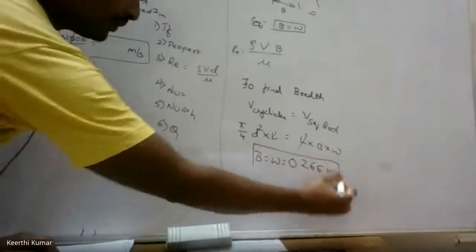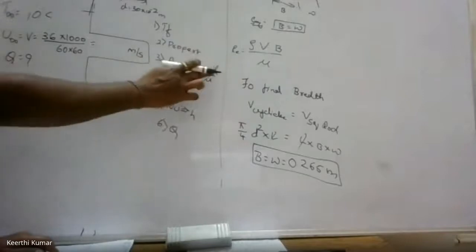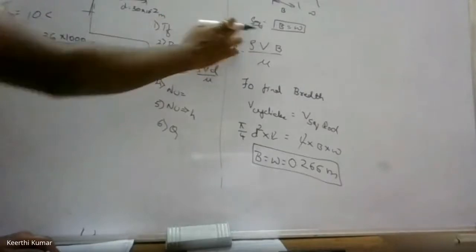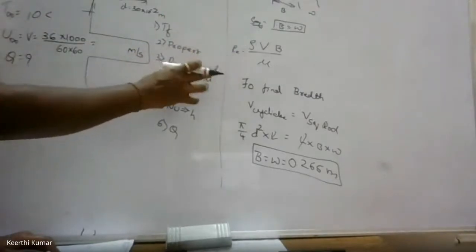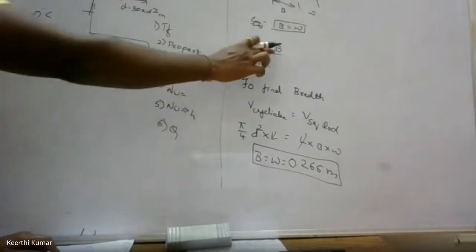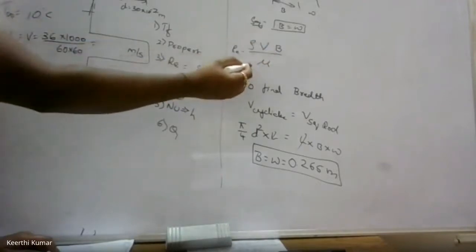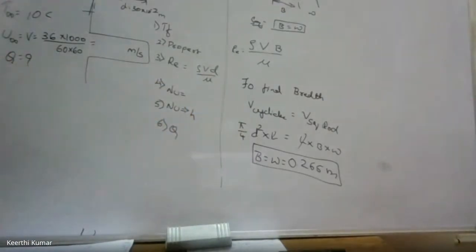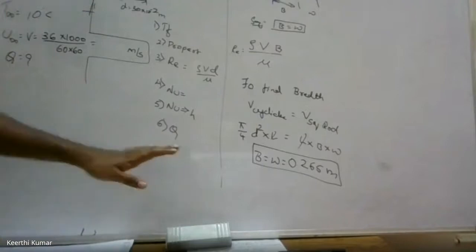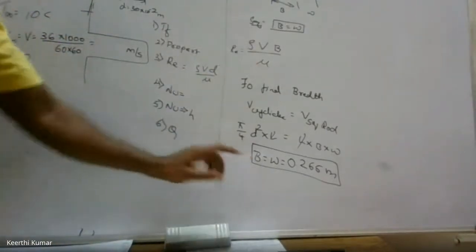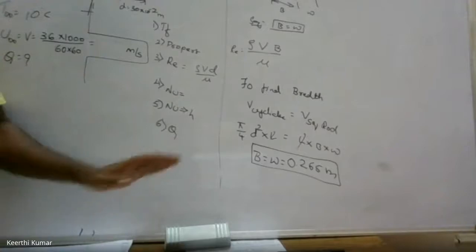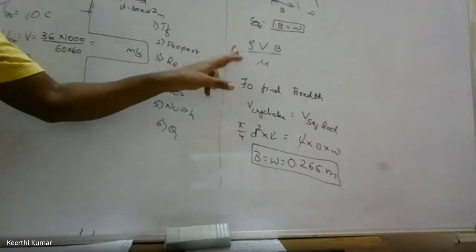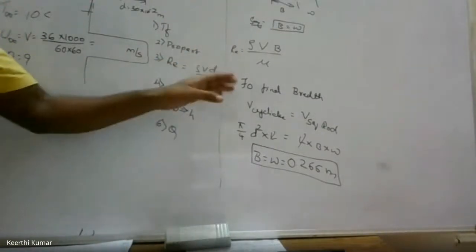So that means you should substitute this B here. Here also TF and properties are not changed. Only in the Reynolds number, instead of D, we are supposed to substitute rho V B by mu. Then go for Nusselt number. Which formula will you use? Okay, see, next class, do one thing. Please be ready with the B. For case 1, find out and get the answer of Q. For case 2, find out till B and also the Reynolds number. Be ready. I will go with further cases in the continued part.